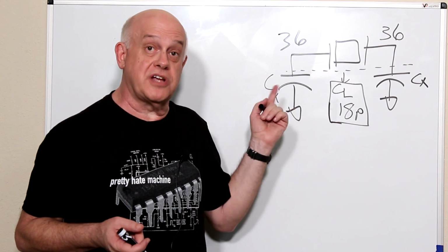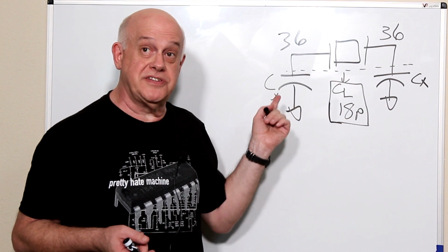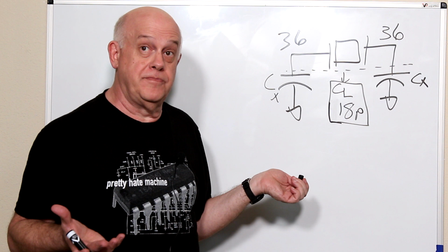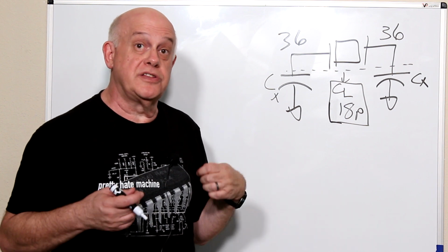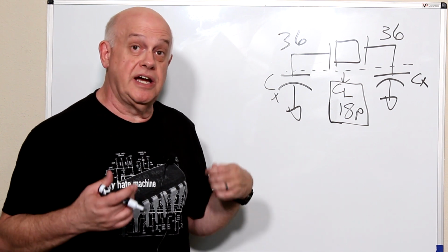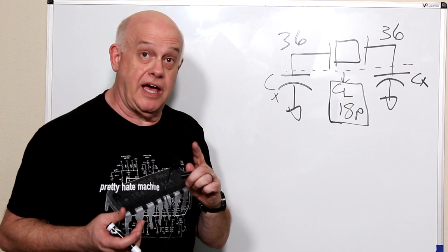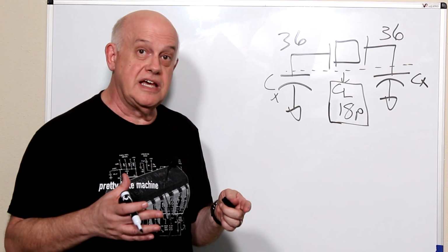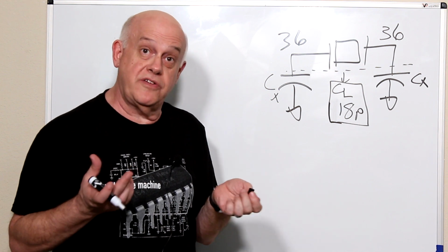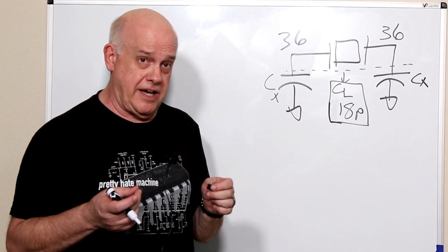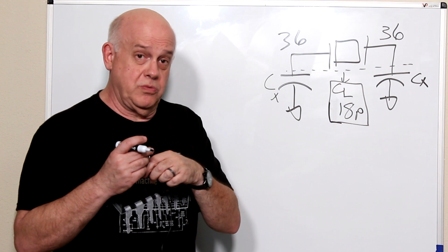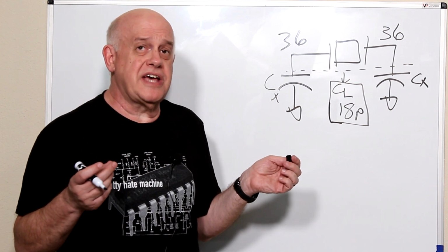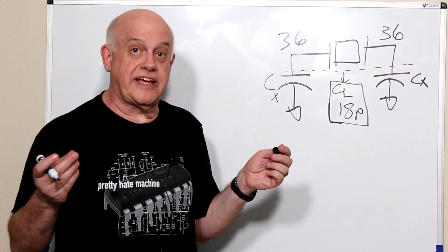The other thing is there's other capacitance to worry about besides the capacitors. What capacitance is there? Well, the first thing is what we call the stray capacitance. And the stray capacitance, like a stray cat, is the circuit board layout. Sometimes it's how well you've cleaned the board. Sometimes you may have said, well, it doesn't say how far apart the crystal and the caps are.